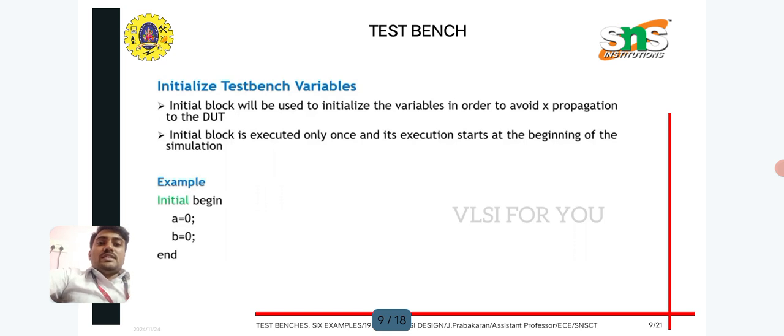Next one is initialize test bench variables. The initial block will be used to initialize the variables in order to avoid don't care propagation to the design under test. The initial block is executed only once, and its execution starts at the beginning of the simulation. Here you can see the example.